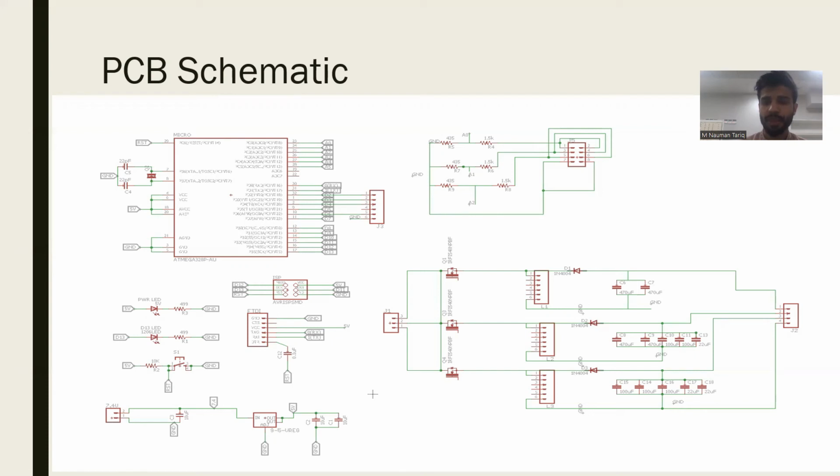When the relay is switched on, the relay output goes towards the input of our MOSFET circuitry, this is our Buck-Boost converter circuitry. The first one is the MOSFET. After that, we have used pins because we have to set the inductor here, and we have designed the inductor on our own. That's why we have used headers for MOSFET circuitry 1, MOSFET circuitry 2 and MOSFET circuitry 3. After that, these 3 are Schottky diodes and the capacitors are connected in parallel to get the desired value. From here, we will get our output voltages.